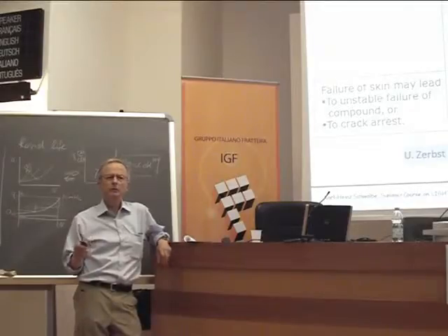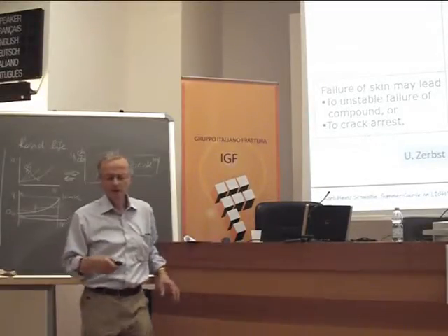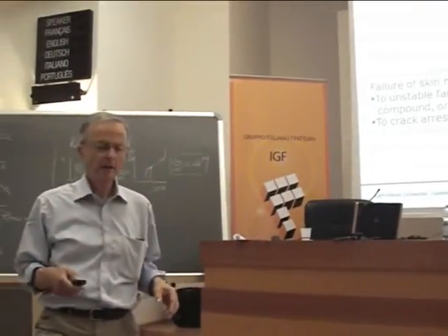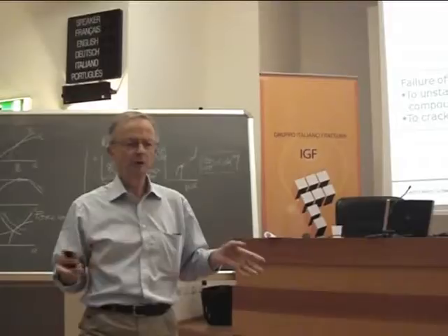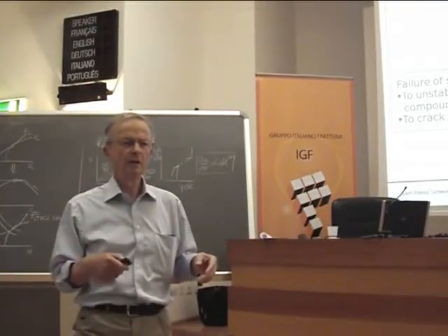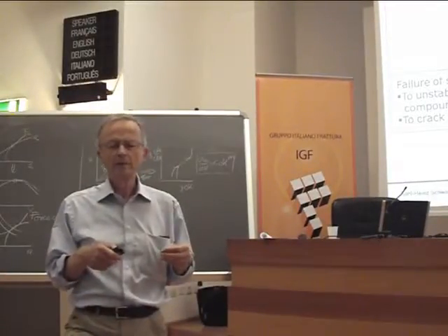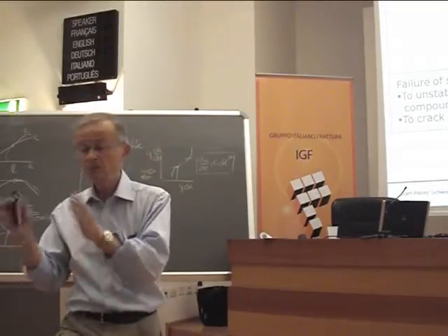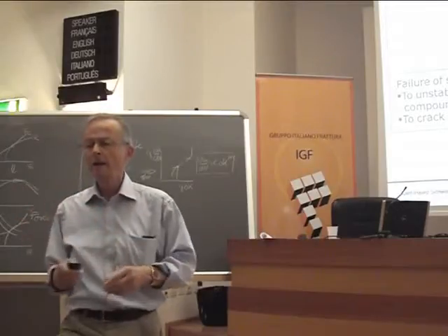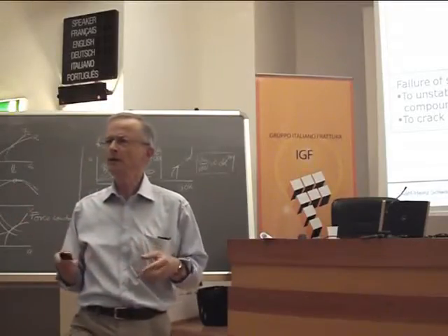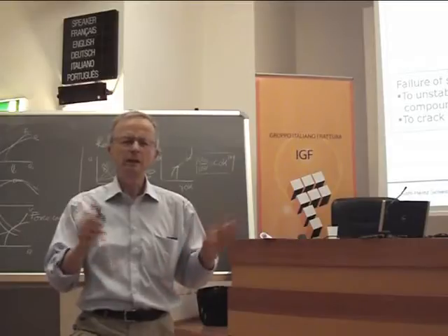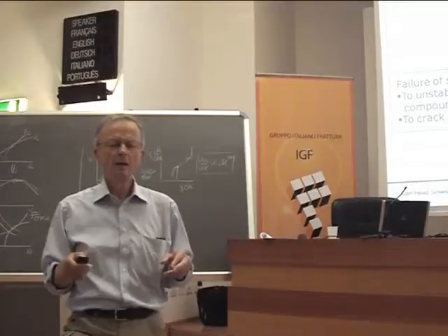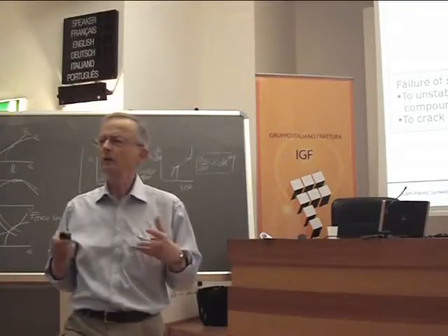And the idea is not too bad, because when you think of a pressure vessel that had seen long service, the inner part of the wall may have been embrittled a little bit by the neutron bombardment. So this is where a crack could become unstable, but be arrested in the rest of the wall thickness, which is really big and where the material has a higher toughness. And it could be that studies have been done, the details I don't remember because it is long ago, and this is in principle possible.